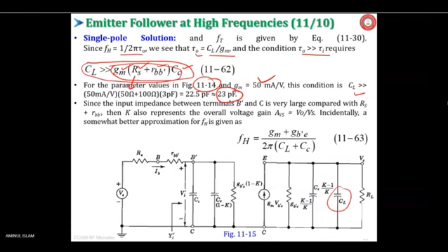We are talking about that diagram and putting that Cl's value. This circuit, the emitter follower, is normally going to drive a capacitive load. It was taken as Cl. But Cl's value should be much greater than this 23 pF. From this estimation, it is coming.